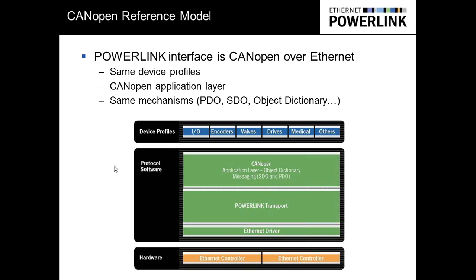With CANopen, it's rare to see a CAN application running faster than 2 millisecond cycle times. In POWERLINK you can be running at 100 microseconds or even lower. We even have some examples where people are running at 30 microsecond cycle times, but that requires some very specialized hardware. The protocol itself doesn't care, it's just about how you implement that communication.